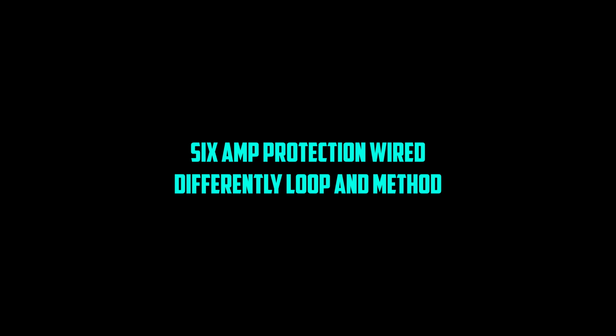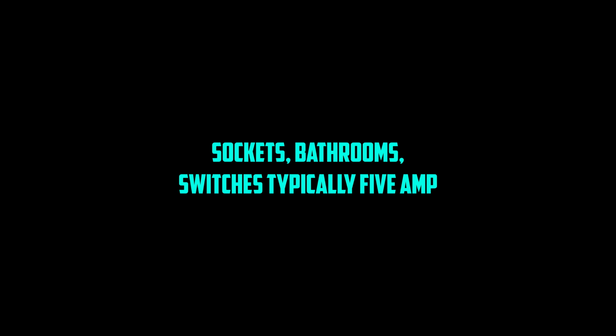Spurs allow adding 1 or 2 sockets off the main ring. Lighting circuits are separate. Yes, lower current, usually 6 amp protection, wired differently, loop-in method. Need multiple circuits so one fault doesn't plunge the whole house into darkness. And accessories, switches, sockets, bathrooms.